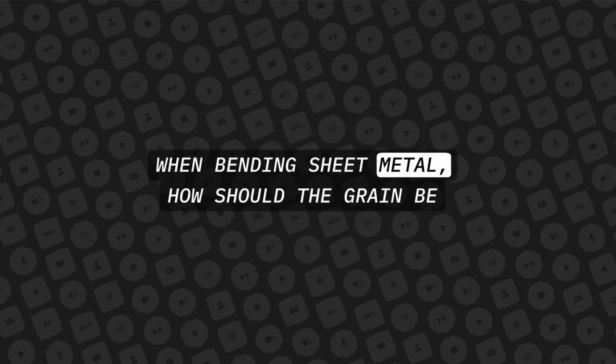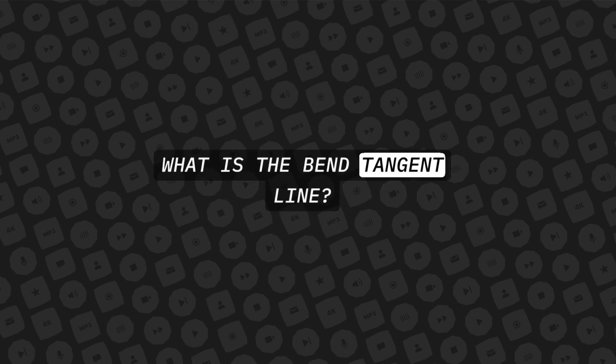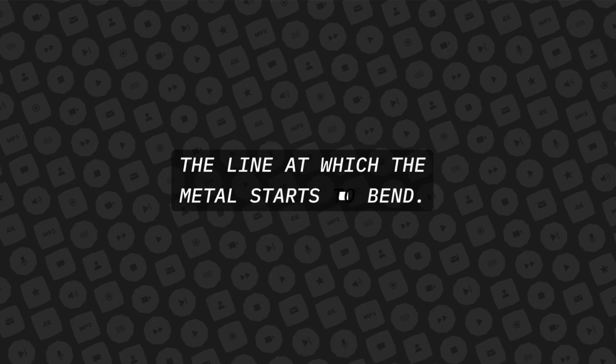When bending sheet metal, how should the grain be in relation to the bend? The grain should be perpendicular to the bend. What is a bend tangent line? The line at which the metal starts to bend.